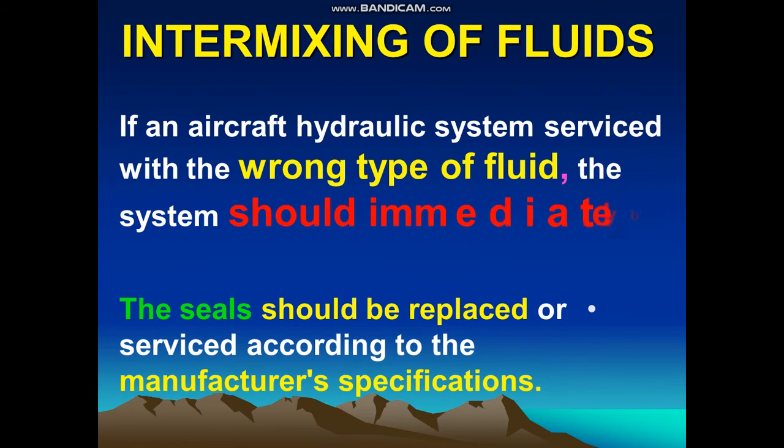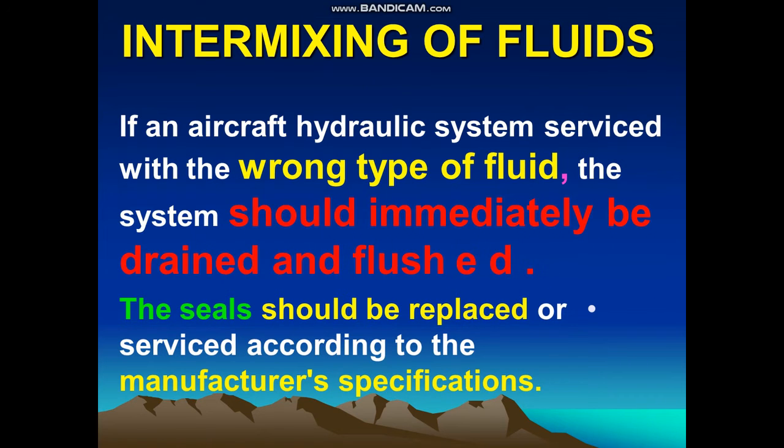Intermixing of fluids. If an aircraft hydraulic system is serviced with the wrong type of fluid, the system should immediately be drained and flushed. The seals should be replaced or serviced according to the manufacturer specifications.